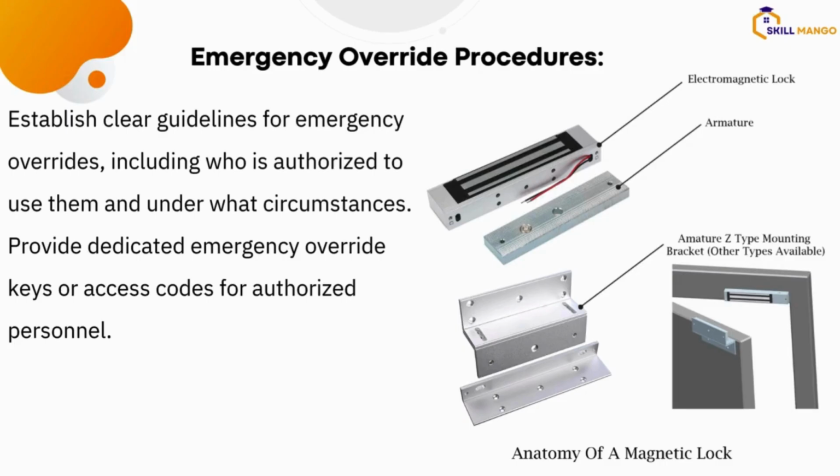As we all know, the maglock uses a magnetic lock and the armature. They connect together, so nothing can separate them. No matter how strong you are, you cannot force them open. So it's important to understand this fact and know that when you cut out power supply to the system, the maglock and the armature disengage and all the doors will be open. All the doors will be open, so people can go out and escape the building.